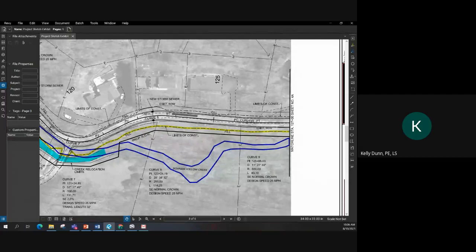But I will say this, also the typical showed a 10-foot lane. And one thing that I learned years ago is, sometimes while a narrow lane might seem like it's going to save you on paving cost and that sort of stuff, one of the things you might run into is it's difficult to meet your spread calculation requirements because your lane is so narrow.